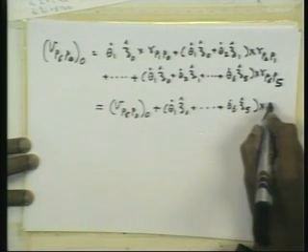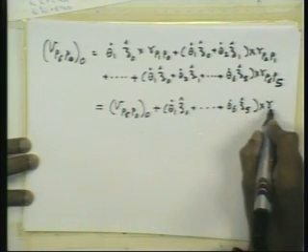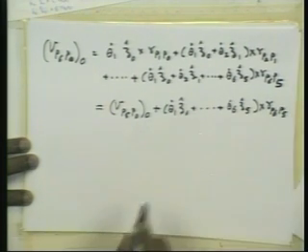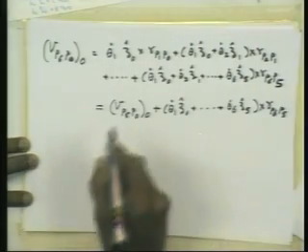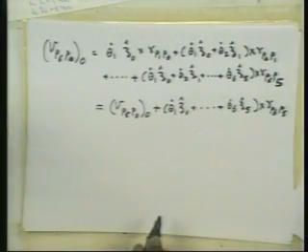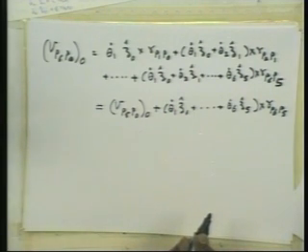And take the cross product of the position vector from P5 to P6, that is P6 with respect to P5. This is of the form, if you remember, velocity of a point on a rigid body can be obtained from the velocity of another point on the rigid body, plus the cross product of the angular velocity vector with the position vector from the reference point to the current point.